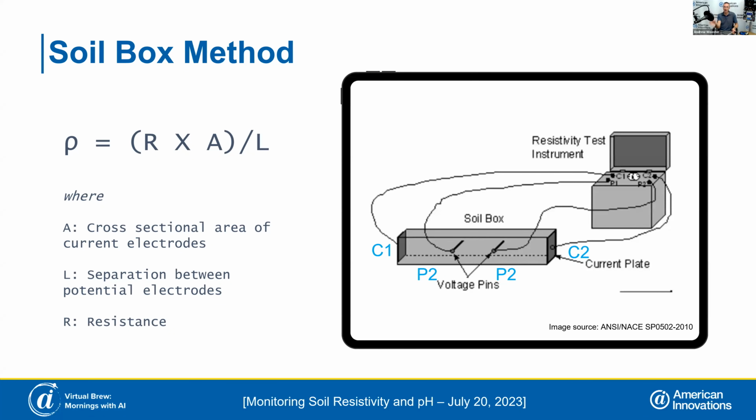It doesn't have a bearing on the depth of where your structure is. So if you took your sample at the depth of the pipeline, then you could get a general idea of what the soil resistivity is at that depth. He's asking about the depth of the pins themselves, not the box.